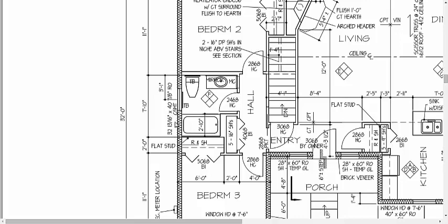Well, what I want you to remember, it's always width, how wide it is first, by how tall it is second. So in this case, if I'm framing this rough opening, I'm going to make it 32 13/16 inches wide by 40 7/8 of an inch tall. I have to maintain that, so my window is going to fit in there.